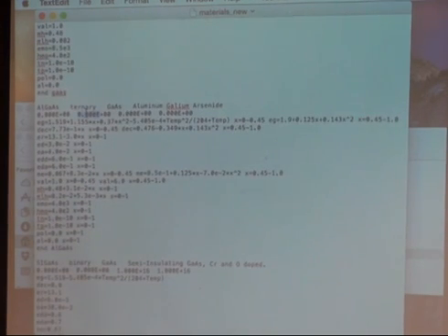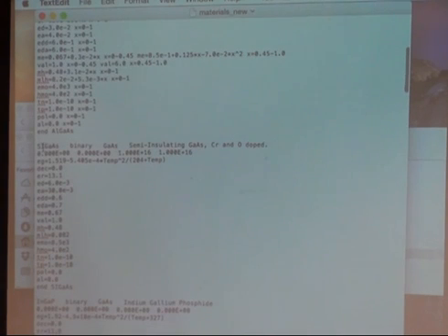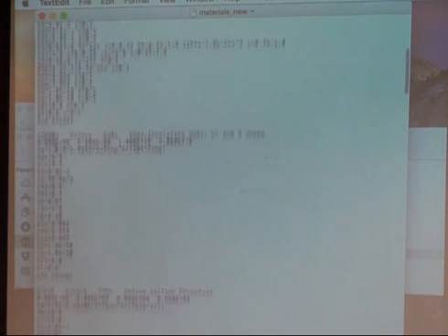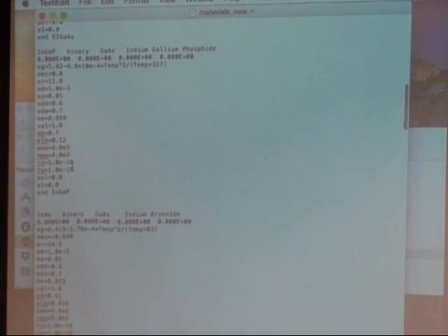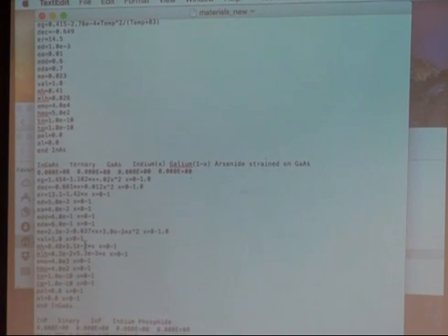Now ternaries, a compound semiconductor alloy, AlGaAs on top of gallium arsenide. Here are some of the properties of it. The band gap, for example, changes with the composition x. It goes from gallium arsenide to aluminum arsenide in certain ways, so it has all this information. It has, very important, new materials, semi-insulating gallium arsenide. This is important because, as I mentioned, it enables HEMTs. Then indium gallium phosphide, used a lot for solar cells, and indium arsenide. And this is completely editable.